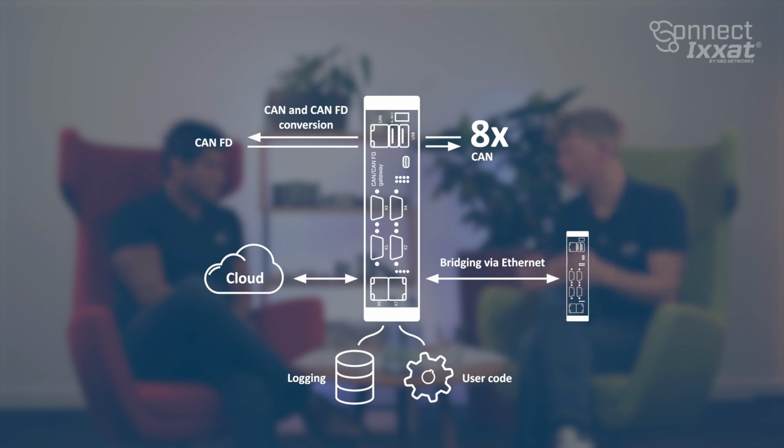Yes, of course. For example, our two very powerful embedded Linux platforms, they are called the Connector or FRC series, and they offer many different interfaces specifically for automotive applications. For example, they have up to 8 CAN interfaces, out of which 4 are CAN-FD capable, or are able to transmit and receive CAN-FD messages. And these two platforms have the functionality of reading CAN-DB files. They are also called DBC files, and these are files where the whole communication that's going on within a CAN network is described. Because of their capability to understand these files, you can do, for example, signal-based mapping. So you can map one CAN signal to another bus, or you can do signal-based logging. But this is a whole topic for itself, and I would strongly recommend you to check out our YouTube channel because we have more videos specifically on this topic.